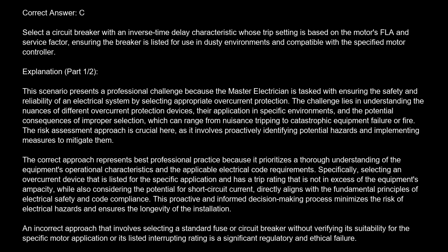The correct answer is C. Select a circuit breaker with an inverse time delay characteristic whose trip setting is based on the motor's FLA and service factor, ensuring the breaker is listed for use in dusty environments and compatible with the specified motor controller.